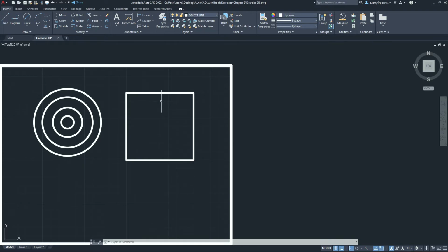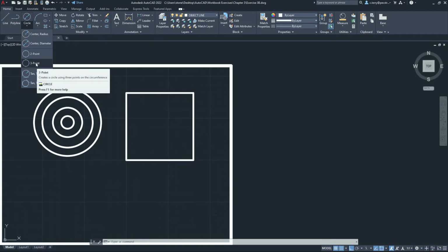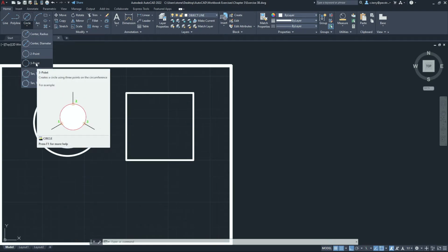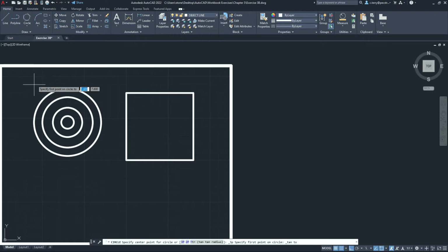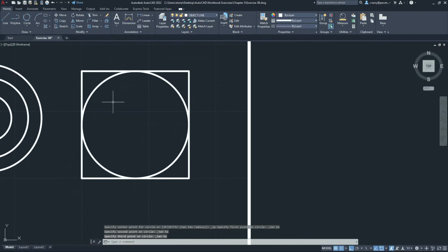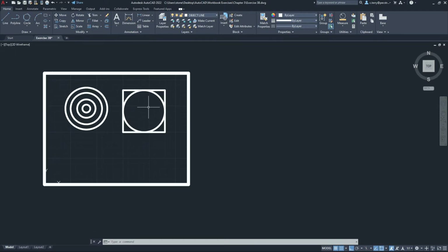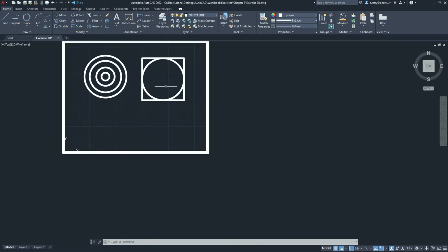So you could do some math in your head if you wanted to and just say, okay, I know the out to out is 3.2, so I could just make the diameter 3.2, but AutoCAD just doesn't want us to do that. They want us to supply a 3-point connection here, or a tangent, tangent, tangent. So I could go here and say, all right, I want that, that, and that. And that's going to give me my circle within those 3 tangents. So I've got it. I don't have to do any math. It's done for me. And then finally, we want another rectangle.